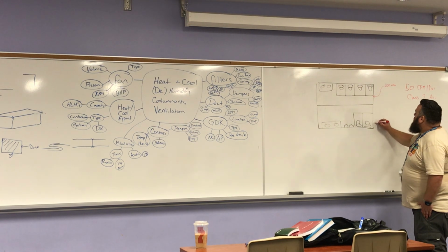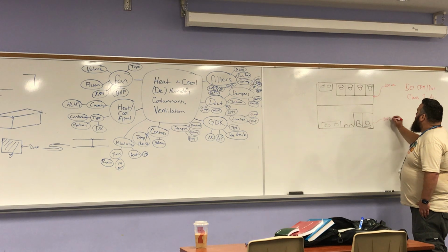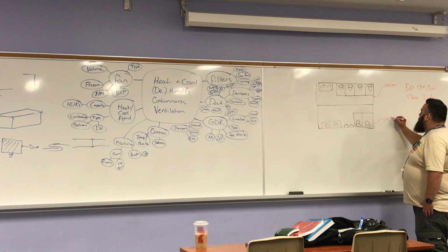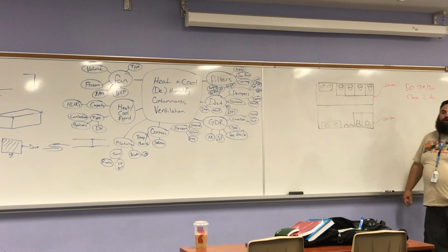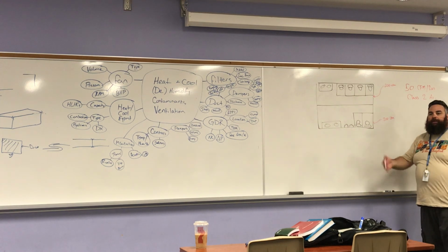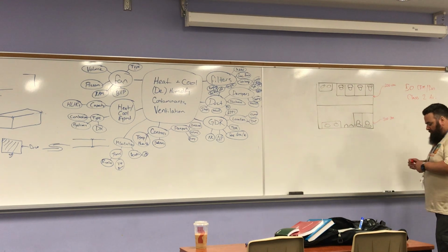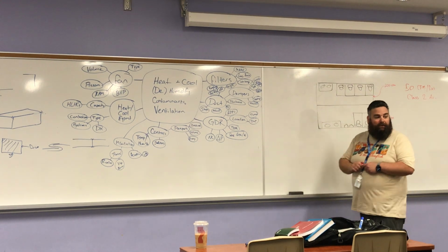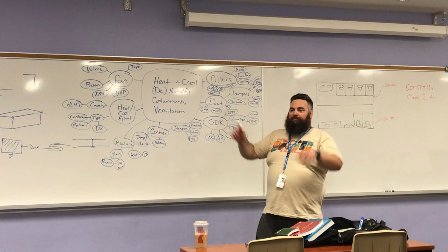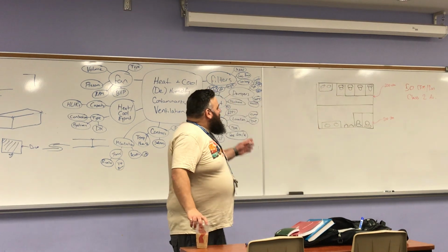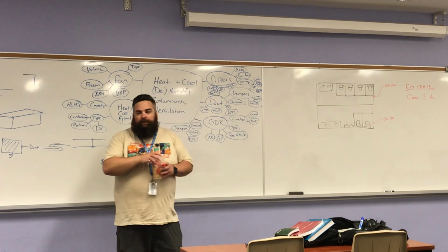Right? Is there no difference between toilets and urinals? Yeah, that's what I was going to ask. No, not under ASHRAE 62.1. They say toilets, urinals, or both. So my total exhaust for both bathrooms? 400. Okay. Seems like easy enough. And we're done. That's the system. Yeah. So that's the volume I need.